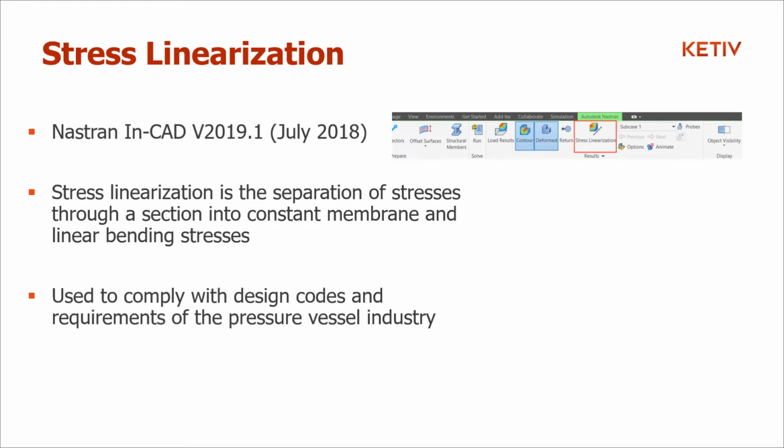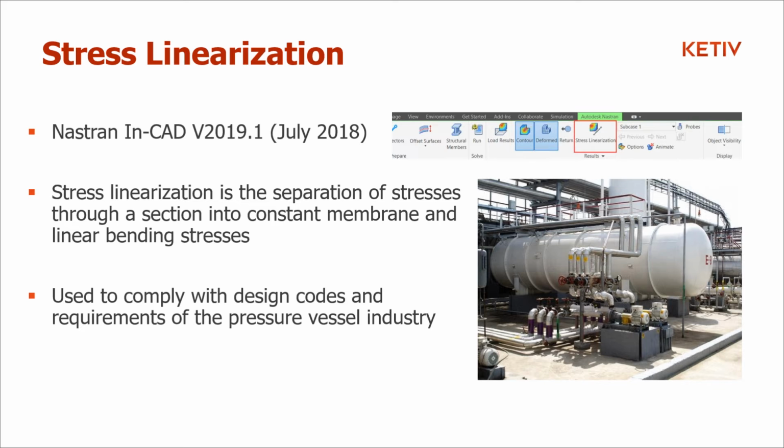It's used typically to comply with design codes and requirements of the pressure vessel industry. You can use the stress linearization utility to graph local stress tensors along a linear path, and/or determine the relative contributions of bending and membrane stress for any kind of structure.